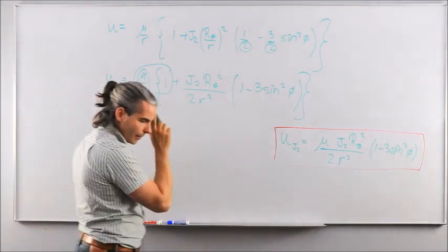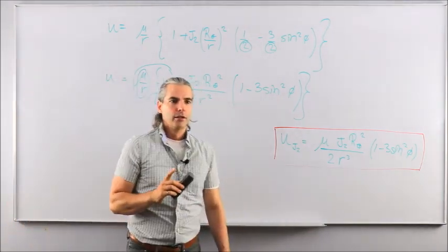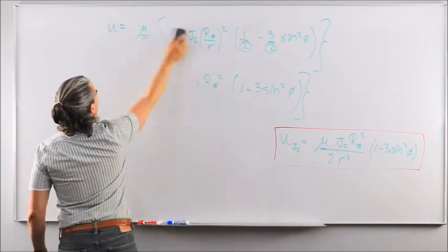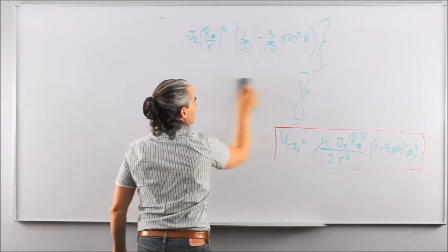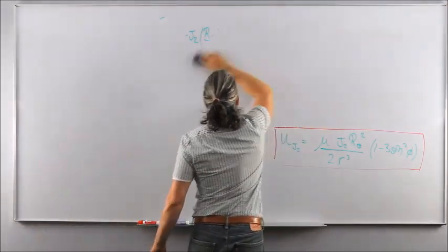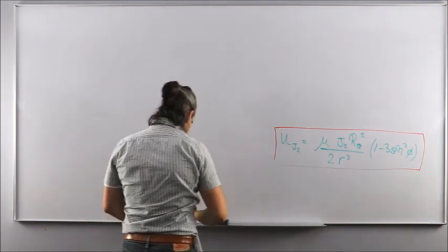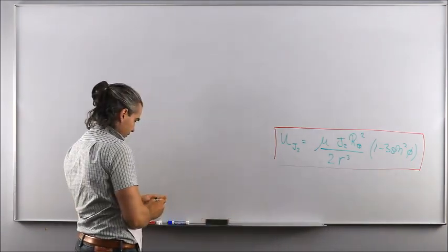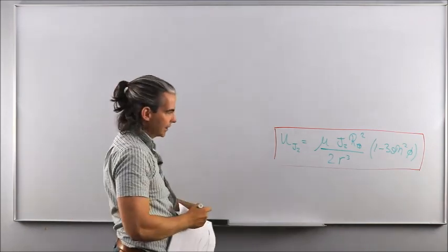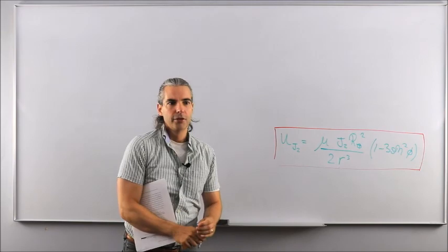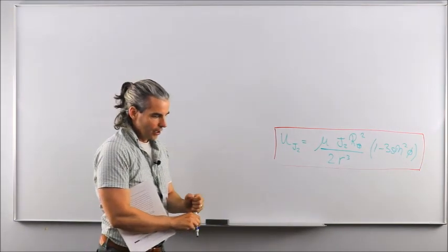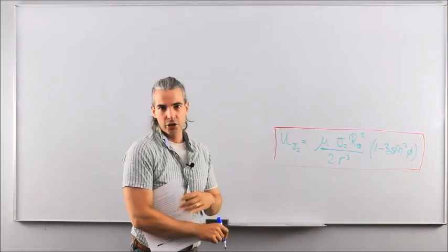Okay, so are we done? What is the purpose of deriving the geopotential function U due to J2? What is the point? Well, the point was to get the inertial acceleration due to J2 on our spacecraft, and call that our perturbing acceleration.